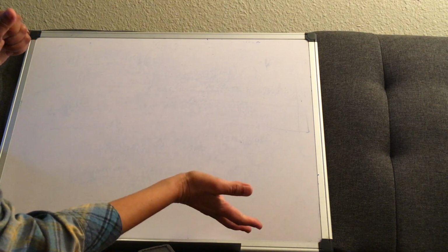Then you make some holes in it. What do you think would happen? From each of those holes, the water is going to flow, right? As you squeeze, that change in pressure has to be imparted to every point in the fluid, so when you squeeze more, the water comes out from all the different holes. Whatever pressure you applied, that change has to be there for the whole fluid. That's one of the examples.